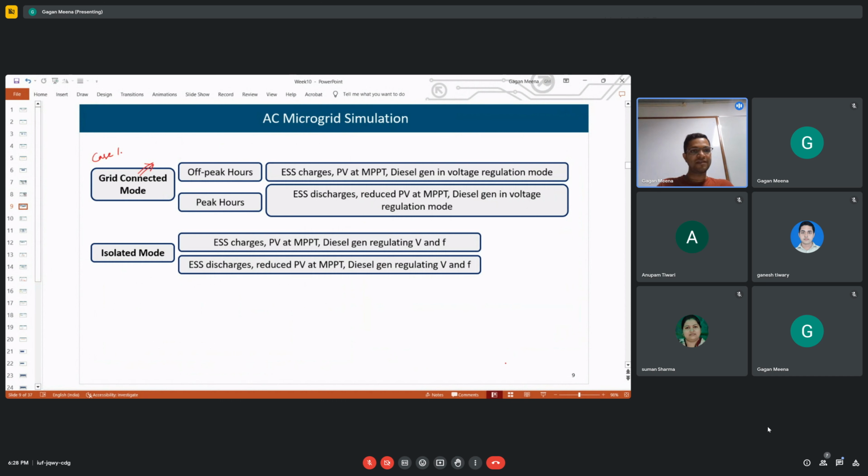Here we have the primary winding, here we have the secondary winding. These two are not electrically connected, but they are connected magnetically, they are coupled, so they have a common flux. So if there is a fault on this side, it will not propagate to the other side because electrically they are not connected.